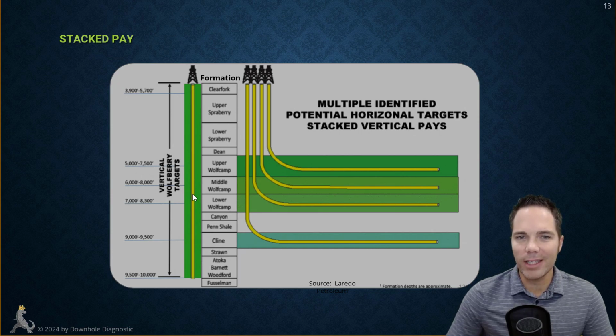Okay, if the fluid level is down here below the TAC and below a lot of the perforations, when you take a fluid level shot, that shot is going to reflect off the TAC, which is above the perforations, and then those perforations are going to reflect a lot of the energy back as well before it can get down to the fluid level. So sometimes it's hard to actually find where the fluid level is in these sort of completions. Also, with a vertical well, you should theoretically, in most circumstances, be able to have perfect gas separation because you can put the pump intake down below the bottom perforation.